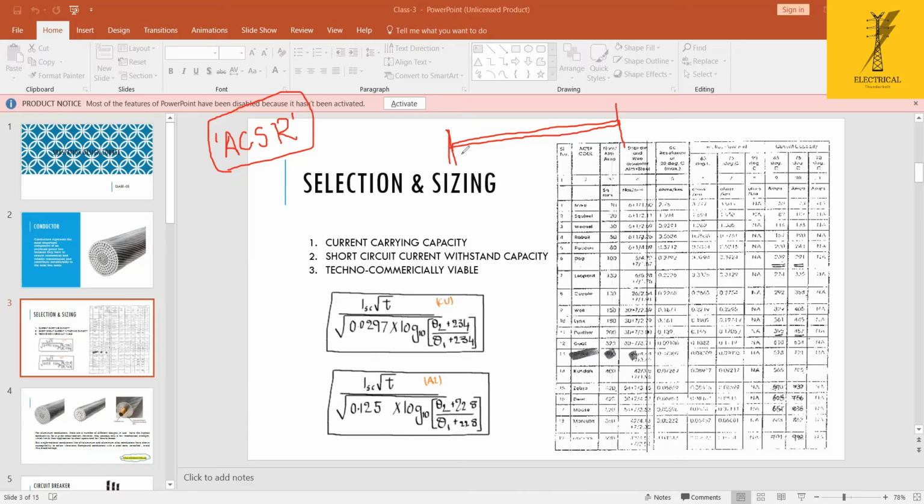From aluminum, we have different types of conductors. Like the ACSR family, where some small aluminum strands are there, and in the middle we have the steel strands. Why are we placing the steel in the middle? Just to give high strength against wind loads or ice loads, to give a good strength for the conductor.